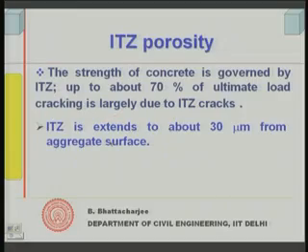That is what it is. Up to even 70% of the load, the cracks that form in normal strength concrete are all at aggregate boundaries, not at one place, but at many places. But at some place where it forms, it further propagates and then joins up the pores beyond 70% ultimate load, and then fracture continues, right, or progress of failure takes place.